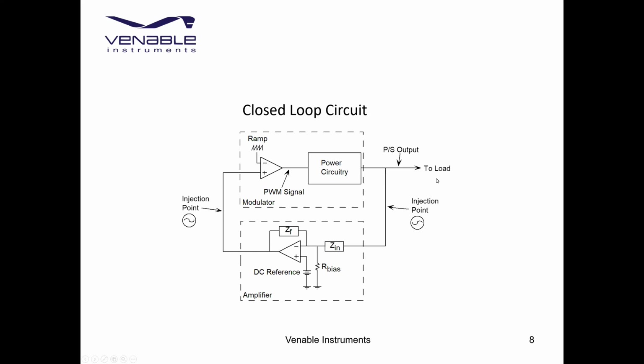That can be a resistor anywhere from 10 to 100 ohms. It depends on how much you want that resistor to affect the set point of your power supply.